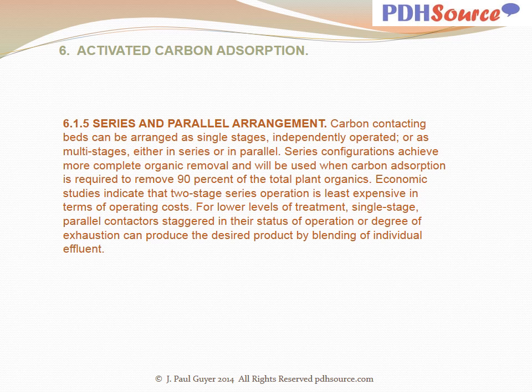Series and parallel arrangement of activated carbon adsorption units are feasible. Carbon contacting beds can be arranged as single stages independently operated or as multi-stages either in series or in parallel. Series configurations achieve more complete organic removal and will be used when carbon adsorption is required to remove 90% of the total plant organics.